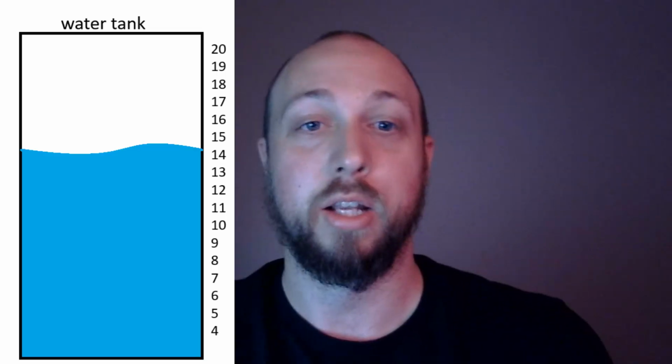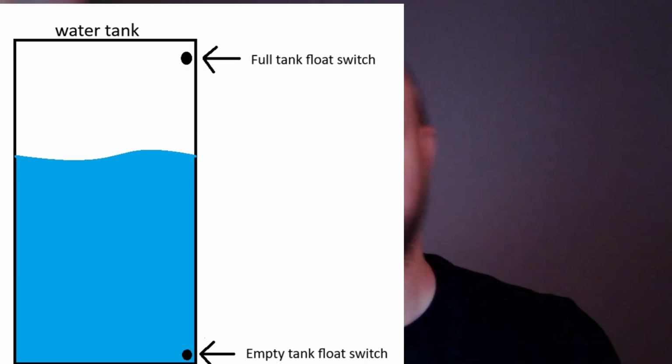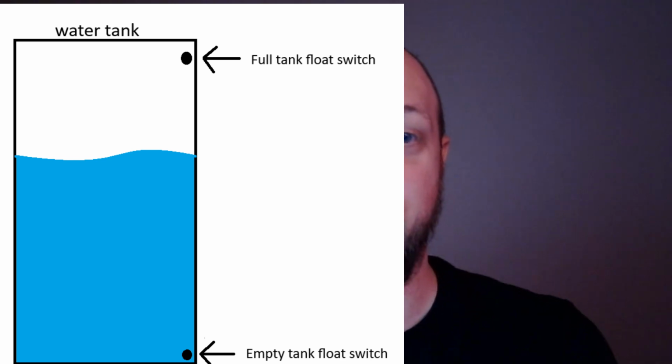So you have a tank and you're trying to read the level of it. If you're reading 4 milliamps, that should mean that the tank is empty. 20 milliamps means the tank is full. 12 milliamps, which is right in between 4 and 20, means the tank is halfway. This is much more beneficial than just float switches saying, I'm all the way up or I'm all the way down. This gives you an accurate range, especially if you have a huge tank.